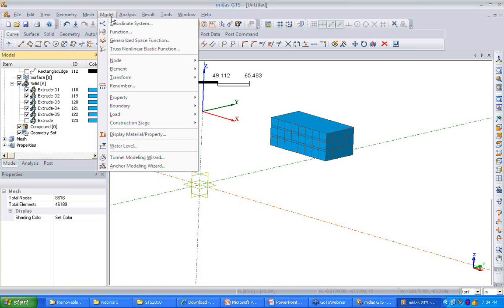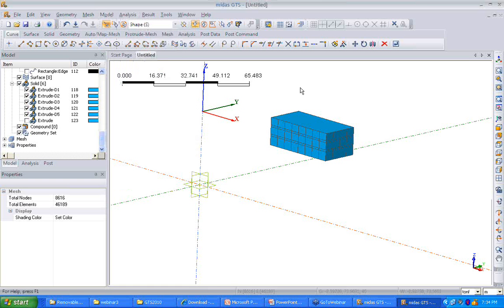So using this concept, I'll be creating my first retaining walls, because in that case I'll be extracting the faces from these solid elements to create the retaining wall. Next, I'll be using the edges that have been imprinted on these solids to create my pile elements.